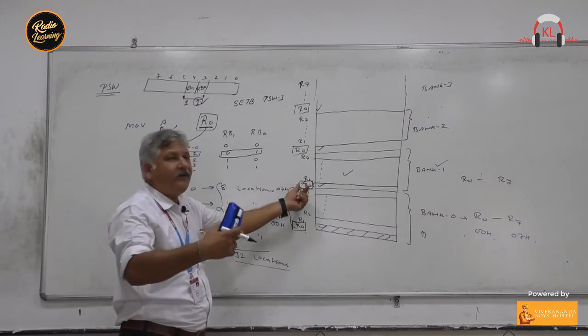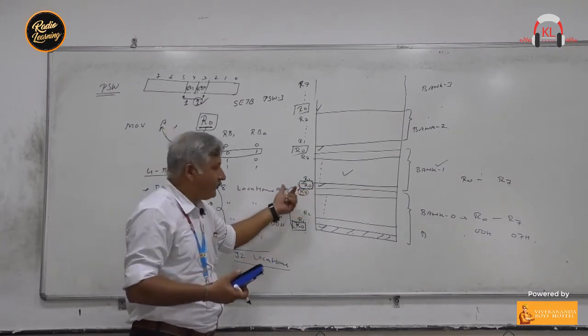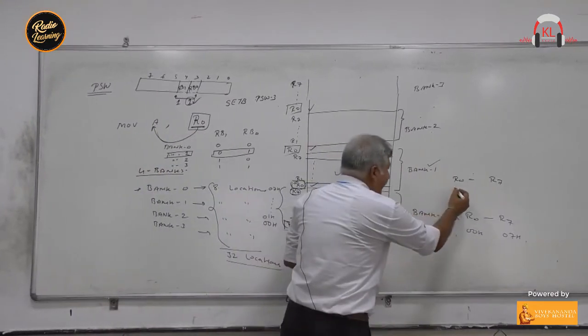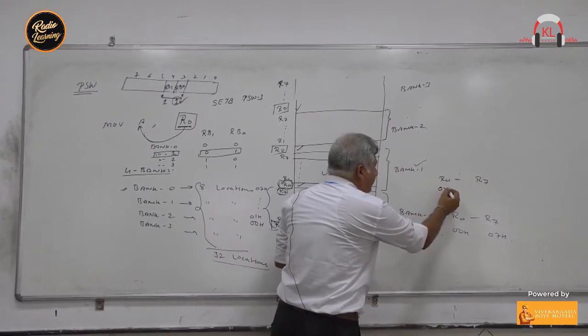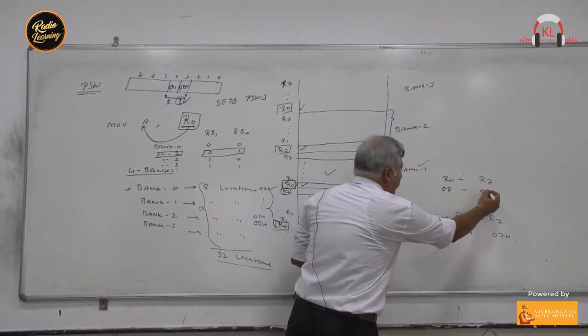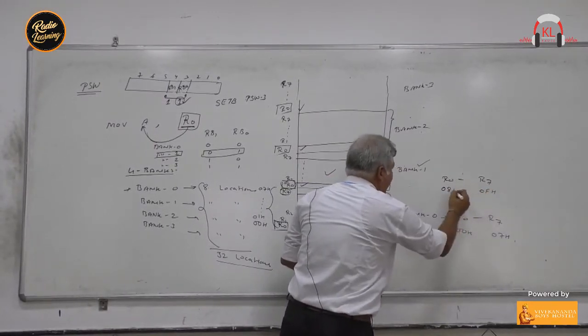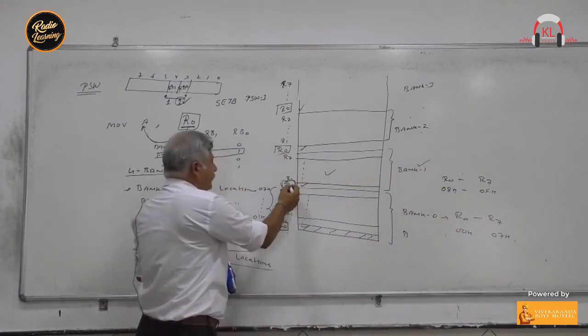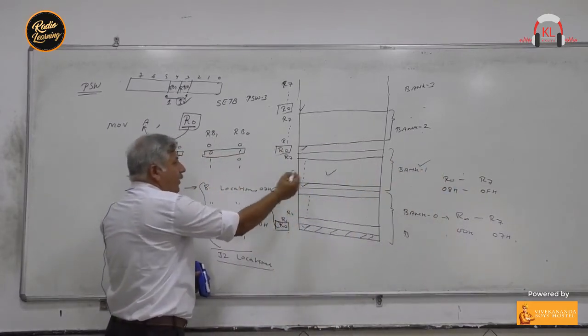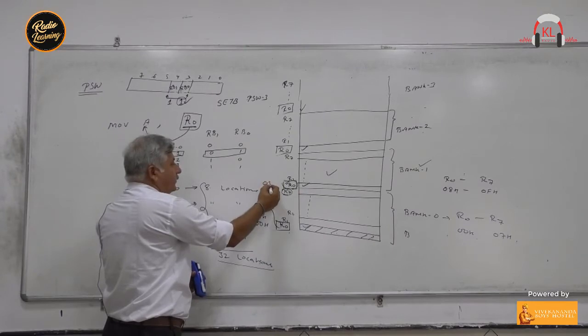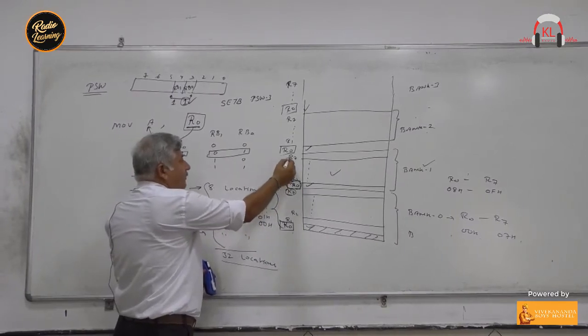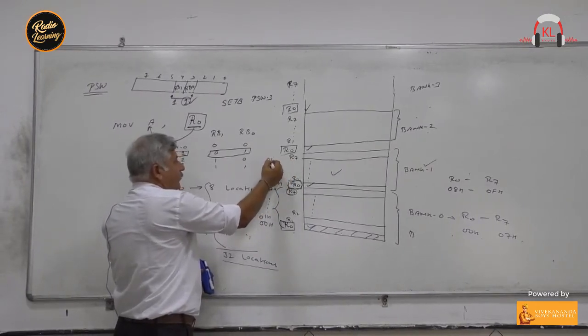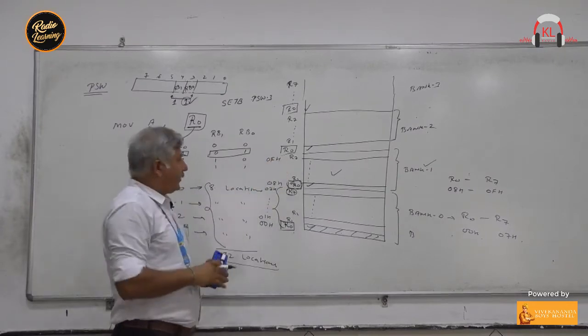The R7 register of bank 0 has the address 07. So R0 will have the next address after 07. The next number after 07 will be 08. So it will go up to 0FH. F means hexadecimal number. So this register R0 of bank 1 will have the address 08H and R7 will have the address 0FH. Right?